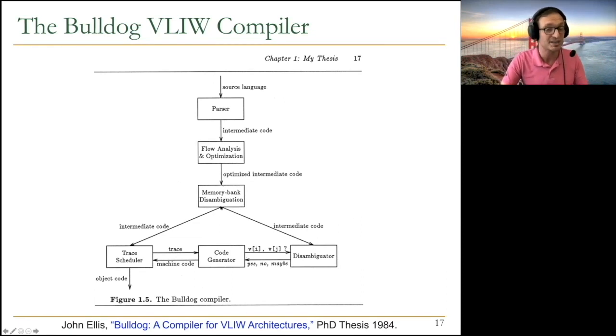If you have multiple instructions concurrently executing, they'd better go to different banks and not conflict with each other in the row buffers of a single bank. And the compiler needs to try to figure this out as early as the 1980s, as you can see. This is a very tough task, actually. This is one of the contributions of this work, but it is a very, very tough task in a machine and a compiler also.